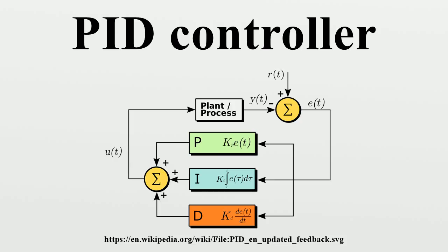If multiple objectives such as short transient and high stability are to be achieved, PID controllers often provide acceptable control using default tunings, but performance can generally be improved by careful tuning, and performance may be unacceptable with poor tuning. Some processes have a degree of nonlinearity, and so parameters that work well at full load conditions don't work when the process is starting up from no load. This can be corrected by gain scheduling.